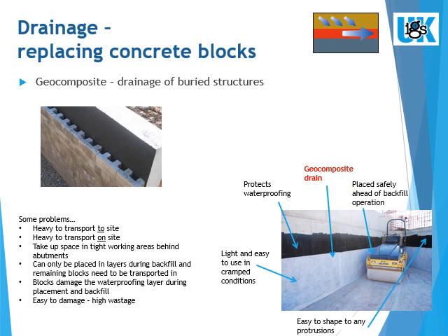This is often achieved using porous, hollow concrete drainage blocks stacked against the side of the wall, which are then filled with drainage gravel. How easy is it to install blocks and gravel behind a bridge abutment? What are the monetary and carbon costs to the project?